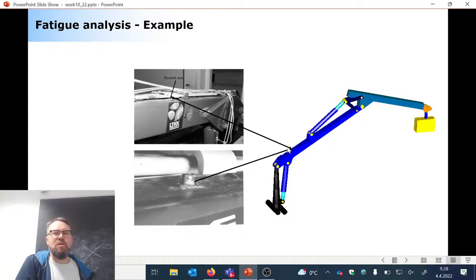You could put it here or here, it doesn't really matter, but not here. This is the worst possible place you can put it, because they play no function other than leading the pipes or making sure that the pipes are kept straight, and you can do that in many other ways. So here's a lecture to you: whatever you're considering, welding is not your friend, it is your enemy. And you need to respect your enemy, because it can make your life very, very difficult.